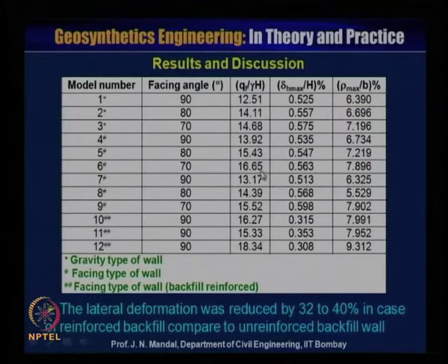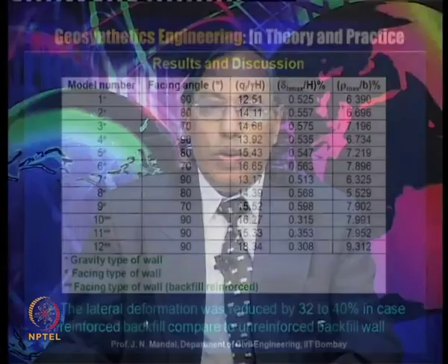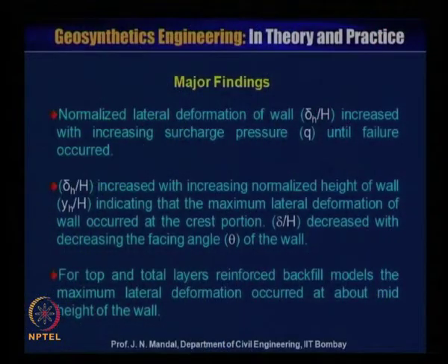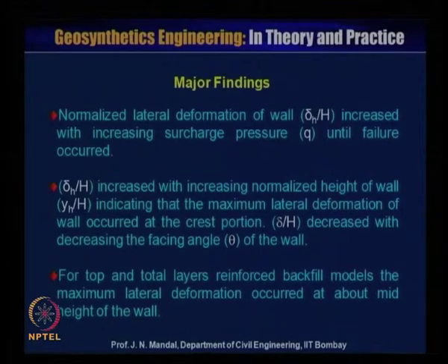Lateral deformation can be observed to be reduced by 30 to 40% in case of the reinforced backfill compared to the unreinforced backfill soil. So, the lateral deformation has drastically reduced. What are the major findings from this experiment? The normalized lateral deformation of the wall, delta H by H, increases with increasing the surcharge pressure Q until failure occurs.